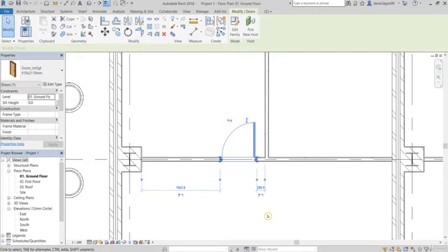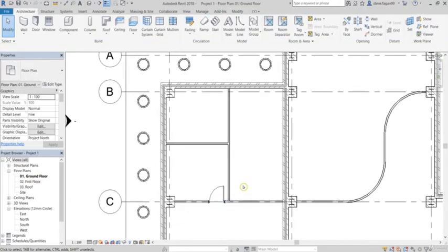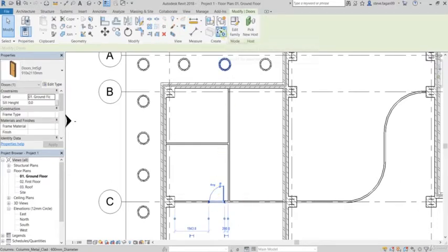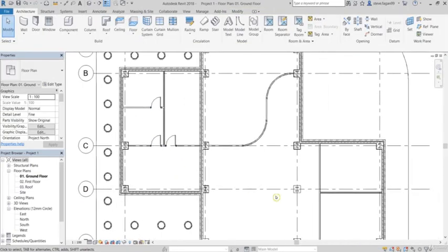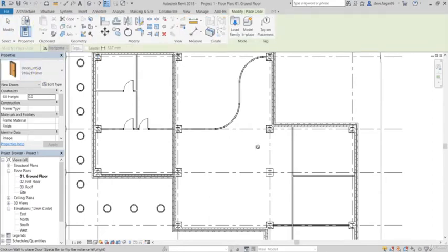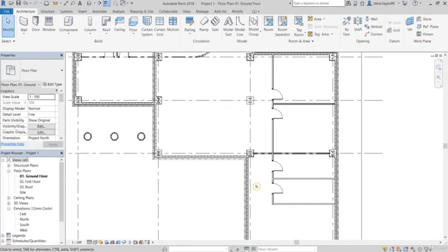So next, if you want to open up the 008 doors PDF, and we can start to place the door 910 by 2110 around our project. They're represented by the number 1. So we have two ways now we can go back to insert those doors. We can either select the door, use our create similar, or we can also use our door tool, and it's the last selected, so we can just go and place. It's best to just place the doors, and then afterwards we'll come back and adjust their position.